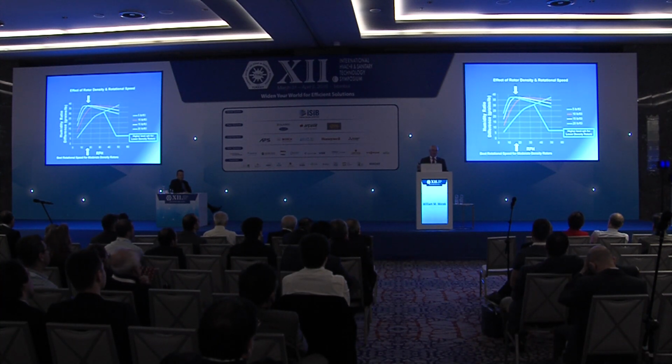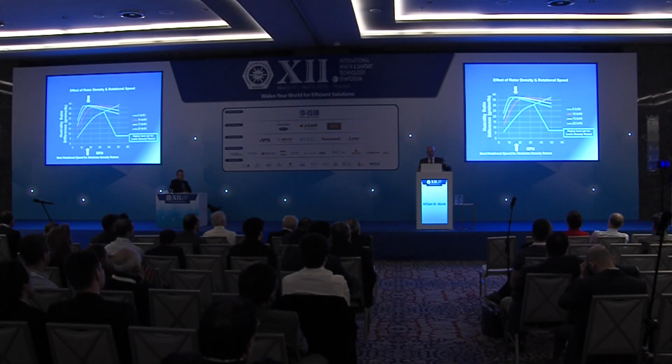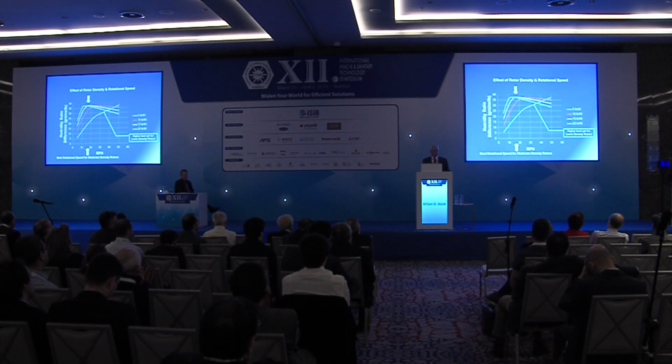That is somewhat of a problem because, remember, every channel as it moves around very fast actually captures some air and does bring it in, so the lighter weight rotors do have higher carryover. But from the standpoint of dehumidification, they don't really change. There can be an argument that maybe the 5 pounds per cubic foot rotor will degrade over time faster because there's less material there, less absorbent than the 20 pound per cubic foot rotor, but no one's ever really documented that.